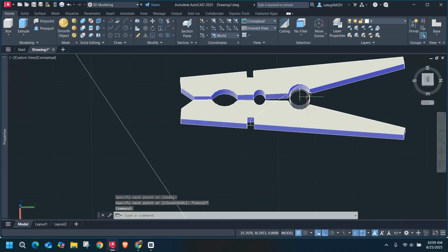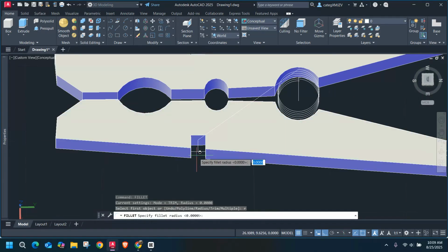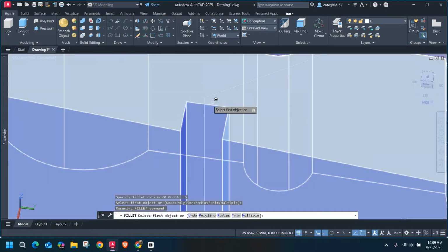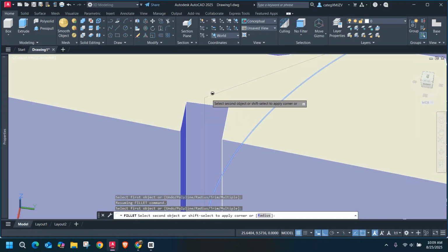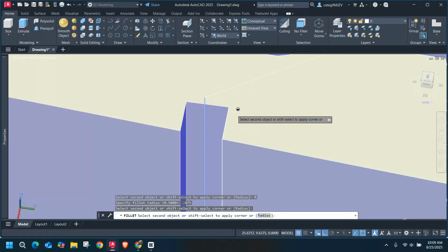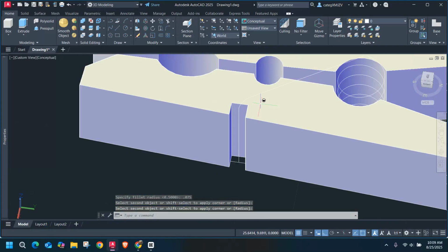Now, you're gonna wanna change the fillet on these. And remember, if it hasn't been changed yet, you're gonna have to change it. So you may have to play with this a little bit. So if I want the fillet to this to that, too much, okay? So go back to radius and change it to like 0.075. That seems better, okay? Click on it and you're happy, okay?